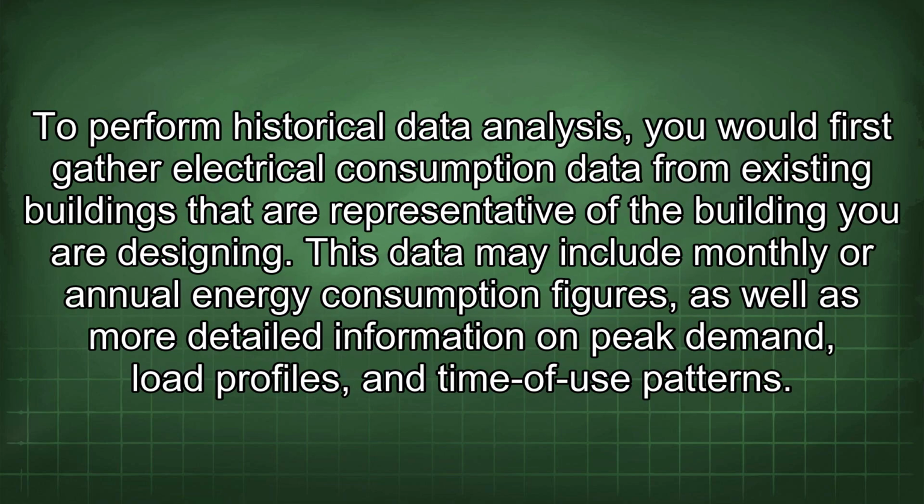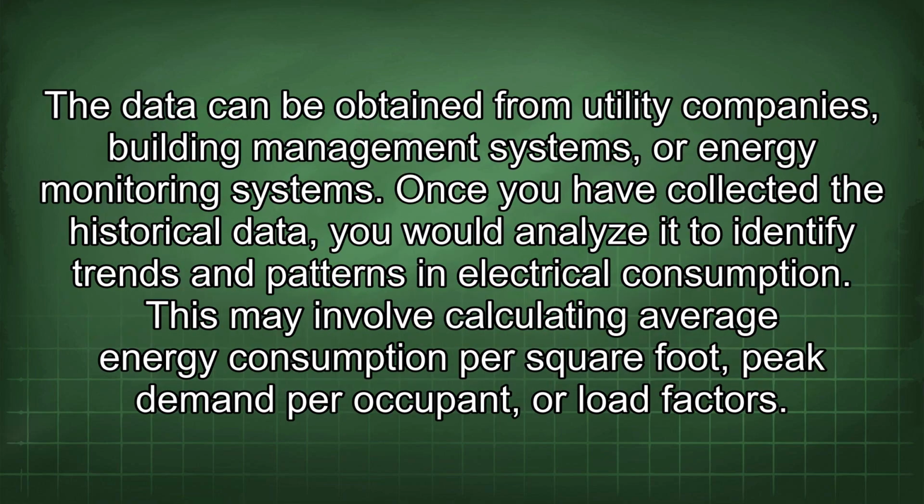To perform historical data analysis, you would first gather electrical consumption data from existing buildings that are representative of the building you are designing. This data may include monthly or annual energy consumption figures, as well as more detailed information on peak demand, load profiles, and time of use patterns. The data can be obtained from utility companies, building management systems, or energy monitoring systems.